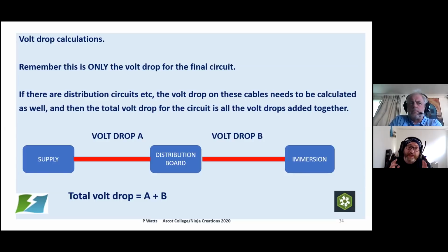And unfortunately, sometimes you do that check after you've just installed it. With MCBs, for example, I had one sent to me on a Saturday job, and I couldn't get it replaced. So now when I'm in a wholesaler, I take delivery, I will do checks, just simple continuity checks to verify the contact resistances are there. Do what you can. But functionality is key. Okay.